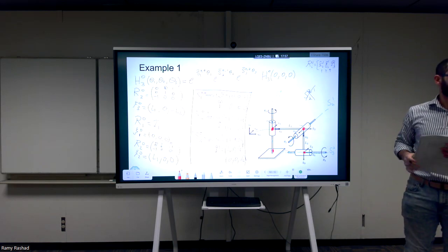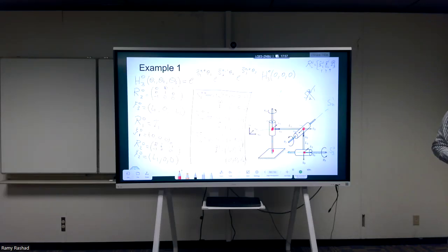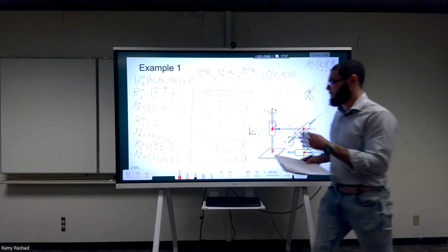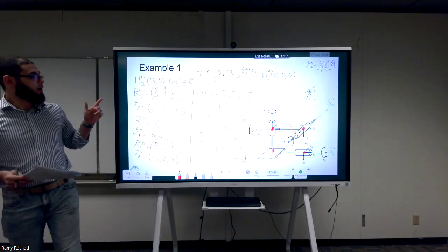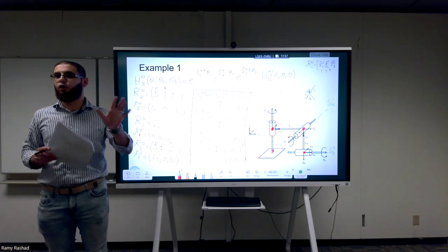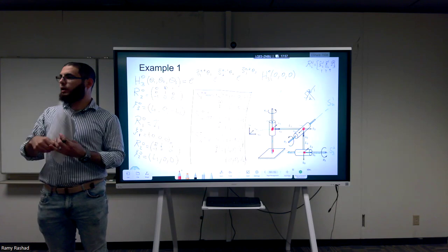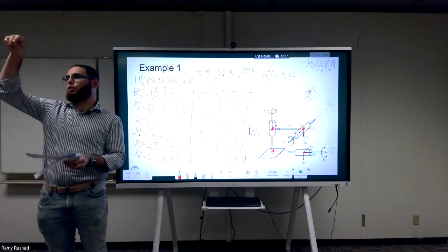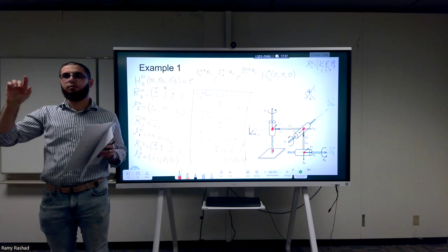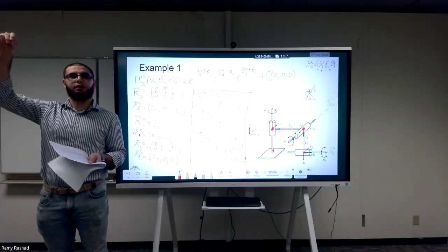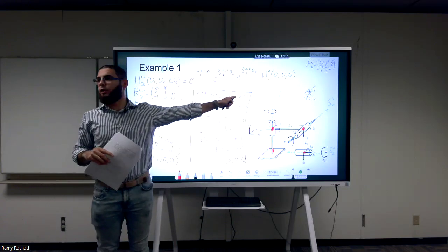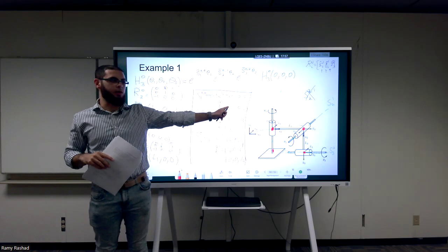Easy? Okay. So, Professor, for the screw axis, if it is a revolute joint, we don't care about the last three numbers being unit vectors. Very good point. When we talked about revolute and prismatic, the prismatic joint had the first three numbers as 0. The second three numbers was a unit vector. So in the end, is S a unit vector or not? Yes. When you have a prismatic joint, S in the end has a unit magnitude. If you have a revolute joint, the first three numbers will be a unit vector, but the second three numbers will not be a unit vector.